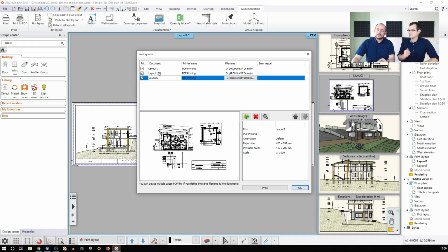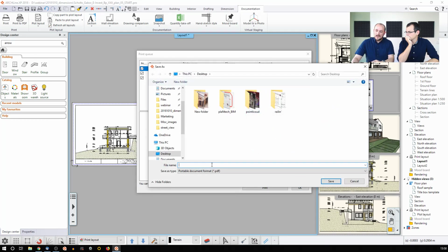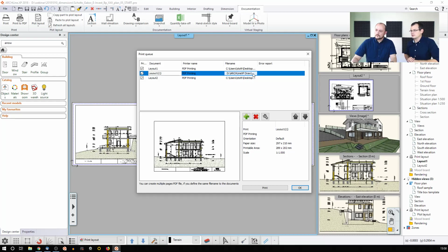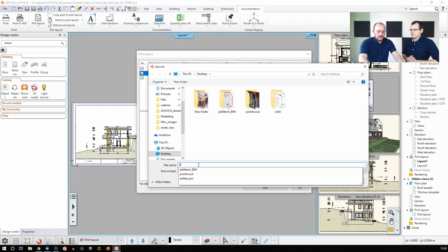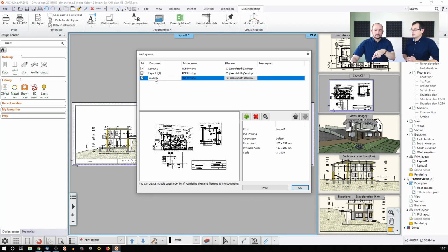Now, I have prepared this earlier using a different file name. Let's just double check that. Okay, because it was prepared on a different computer, I should just make sure that I use a different name. This should be, again, I think I use this name. And for the one in the middle too. And for this one, it should be the same, PL01. And the reason I'm using the same file name, because if I do that, the software will add these as pages to the same document. So it's going to be one PDF document with several pages.